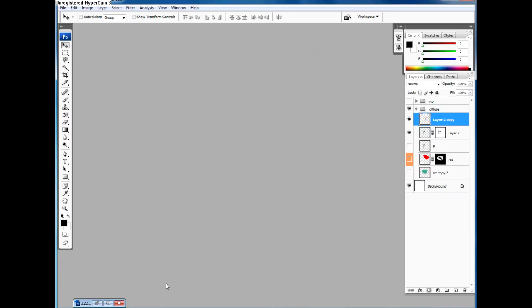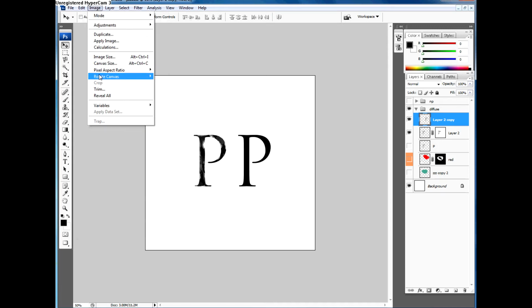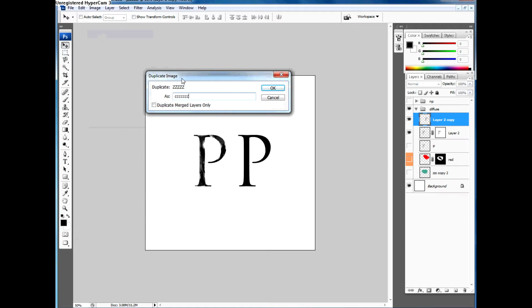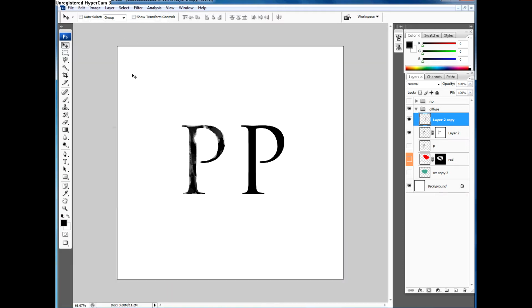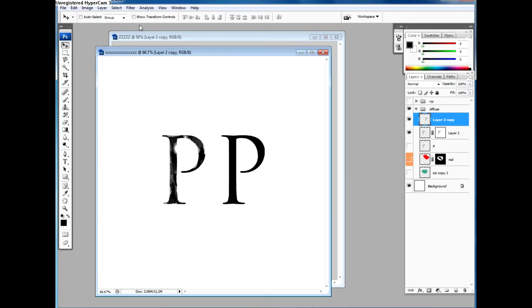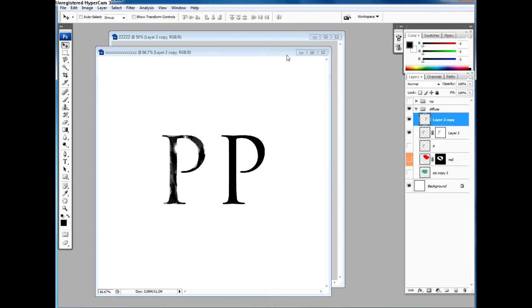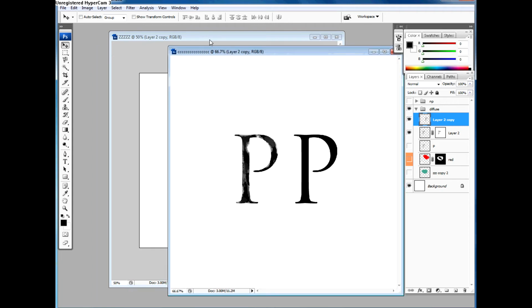So you've got minimise and maximise windows. You can maximise it again. But sometimes if I've got a few windows in the scene, like if I duplicate, I've got quite a lot in the scene then, and I can't easily select between the two. If you hit F on the keyboard, you don't really see exactly what that means because this region I'm recording isn't my whole screen, but that will flip through the different full screen views to see different canvases and that kind of thing. So if ever the canvas view isn't what you want, hit the F key.